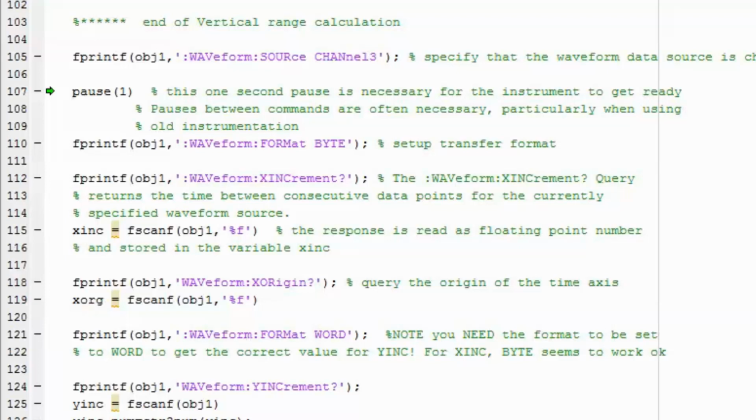If you run your routine and errors are generated, and then you switch to running your routine step by step, and there are no errors generated, that means that you have to insert delays in some places to be able to have the acquisition working correctly. So if you get inexplicable errors, always run the code step by step, and if you don't get the same error, this means that you may need to insert specific delays to allow the instrument to set the parameters that you've asked it to set or execute the commands that you've sent.